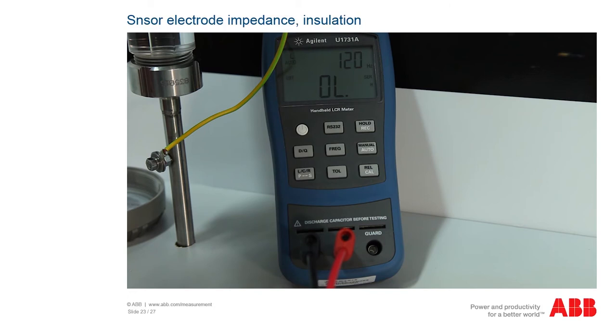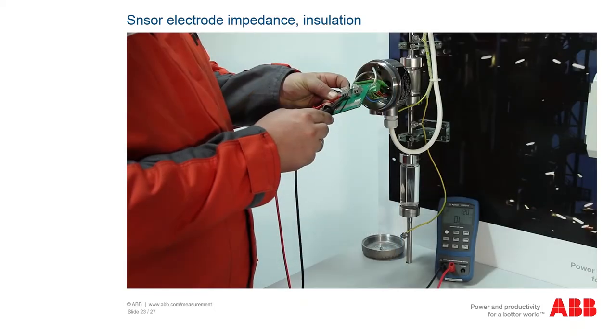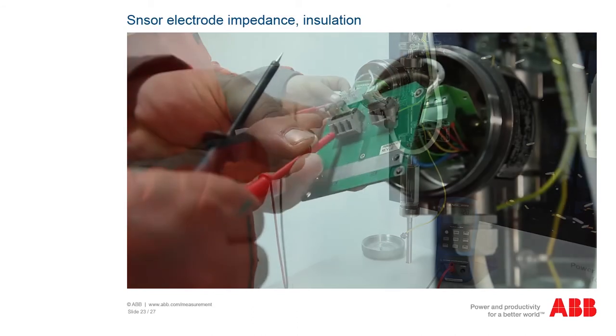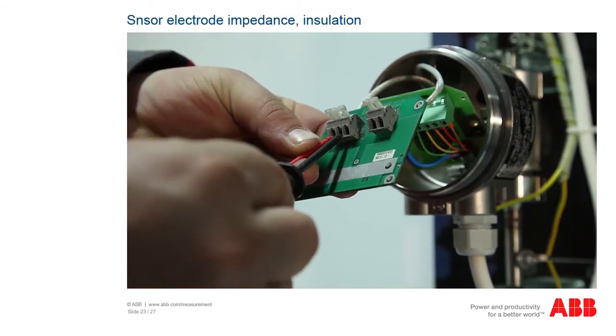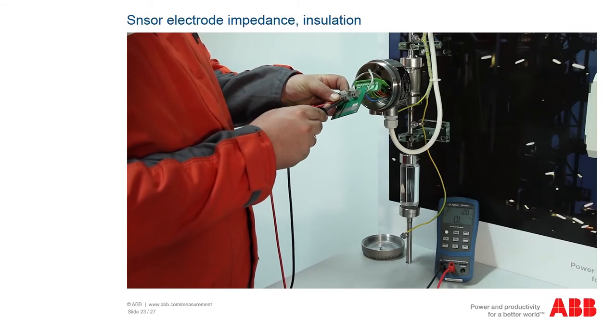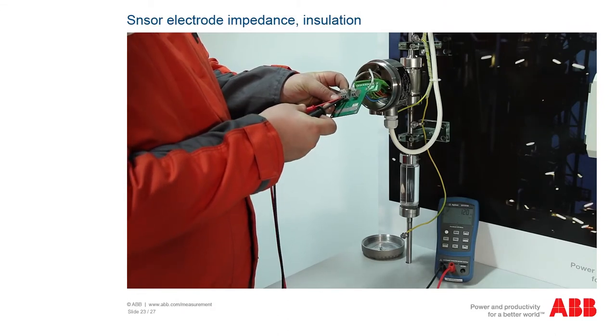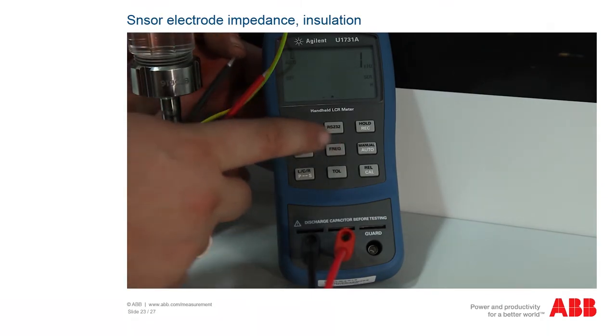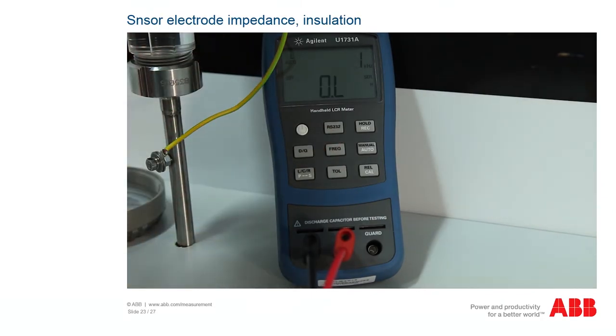The electrode impedance is measured with the LCR. To do this, set the LCR meter to impedance measurement at a frequency of 120 Hz. First, measure between contacts 1 and 3 of the wider connector on the XE board for the impedance of electrode 1, and then between contacts 2 and 3 for the impedance of electrode 2. Then measure directly between contacts 1 and 2 for the impedance between the electrodes. Perform the measurement again with a frequency of 1 kHz and enter all values in the measuring log.